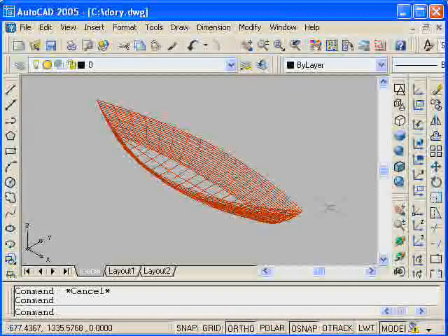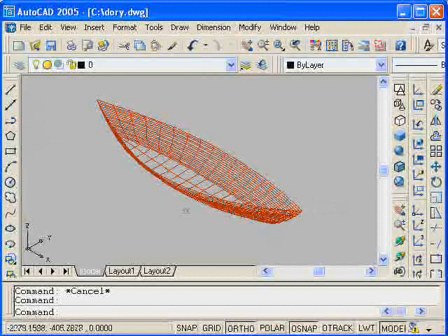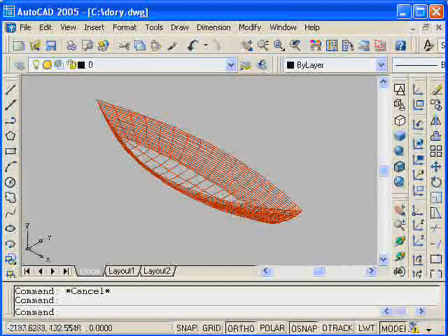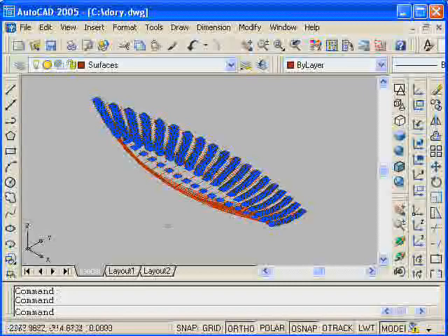We'll create a surface model for a hull form. Seen here is a surface model of a traditional flat-bottom boat. The surface model consists of 4 different surfaces. A surface on the side, and then one on the bottom were first created. Then these surfaces were mirrored about the x-axis to form the other half.